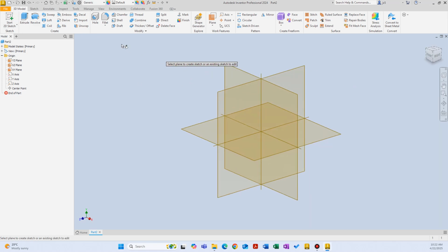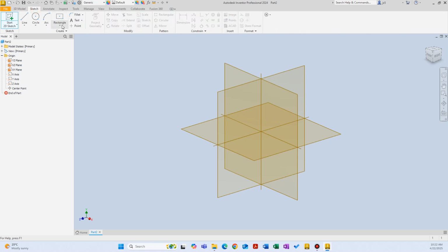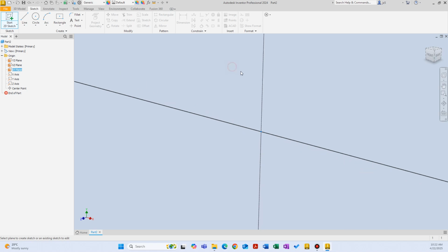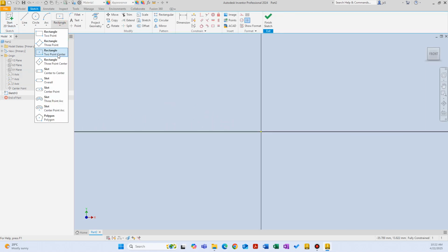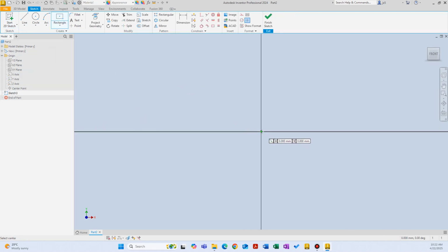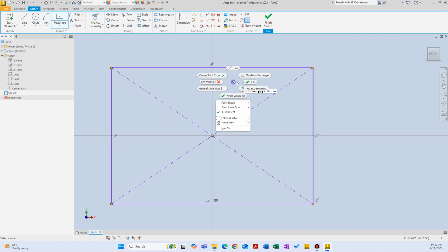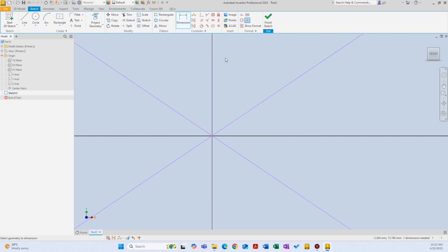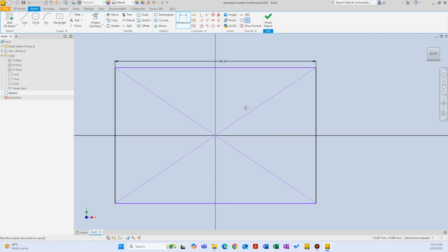So let's start a sketch, and let's use the 2-point center rectangle. First, let's select the XY plane. Let's use the 2-point center rectangle. That way we take advantage of that symmetry. Right, dimension this. Right now my measurement units is set to millimeters, but I want to design it in 4 inches. So I manually typed in 4IN.